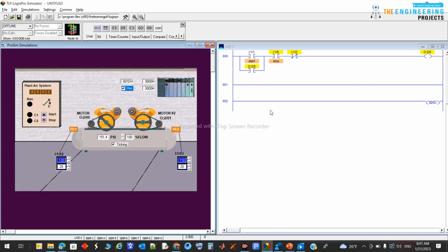Again, also one thing we need to add is the indicator that the compressor is working. So I need just here to put one parallel branch to show also the indicator. So this one is working. So another output. So this output will be here in parallel to have this C1 also running here. So let's run and see what's going on now.